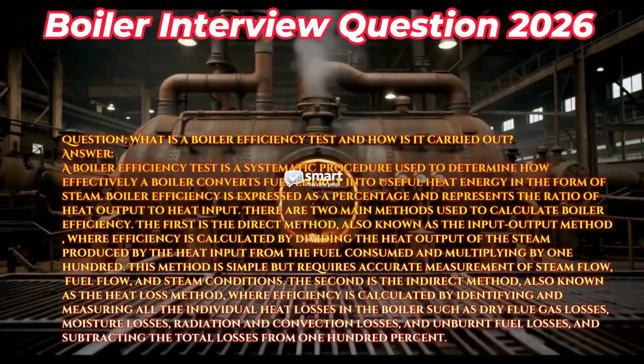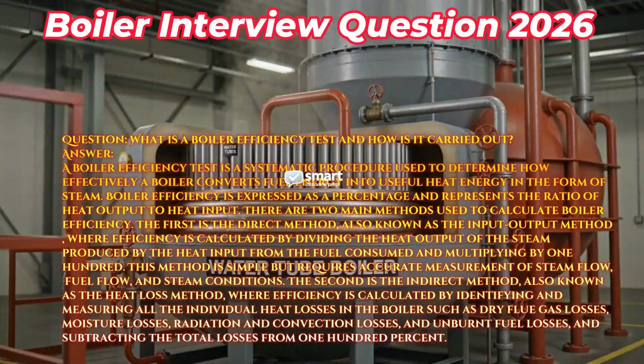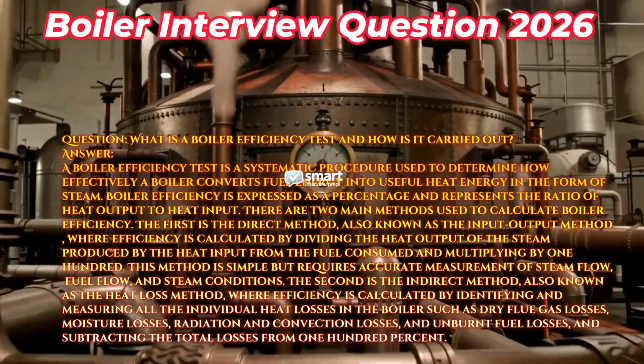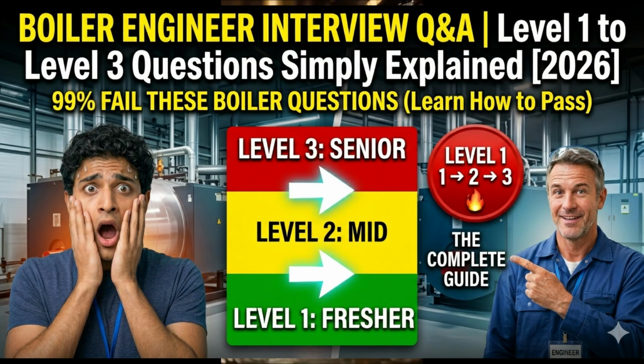The second is the indirect method, also known as the heat loss method, where efficiency is calculated by identifying and measuring all the individual heat losses in the boiler, such as dry flue gas losses, moisture losses, radiation and convection losses, and unburnt fuel losses, and subtracting the total losses from 100%.